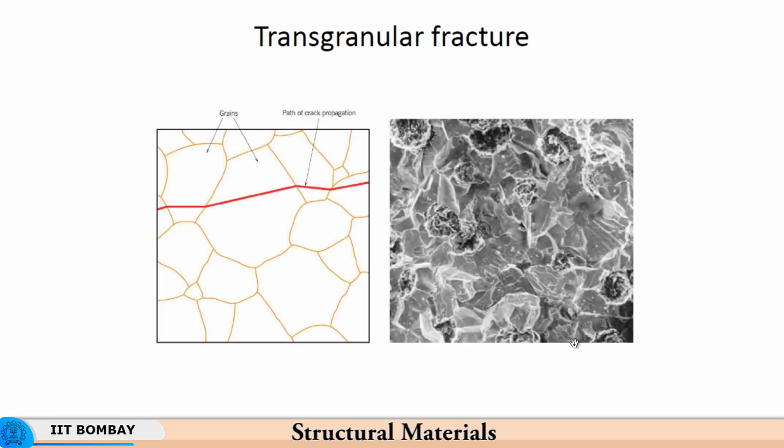Well, you can have a fracture taking place under shear, like in case of shear lip which I mentioned to you earlier, where the fracture takes place over an extremely small amount of strain, in which case you will see these shear facets, without any dimples or without any evidence of voids having grown and the material having failed by void coalescence.